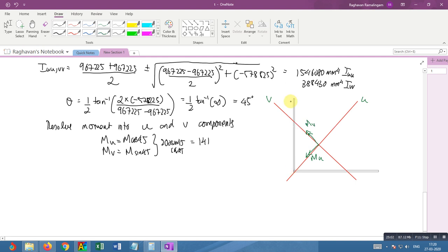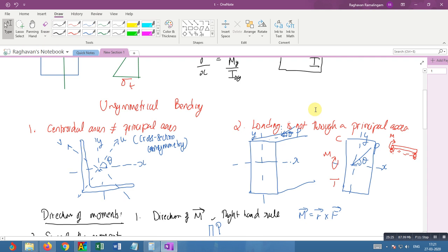You see that your thumb is going this way, and keep your fingers over here. You see that it goes. This is how your fingers will curl over. Now, what you can observe from here is the parts to which this arrow mark is pointing, those are compressive. The parts away from the arrow mark are tensile.